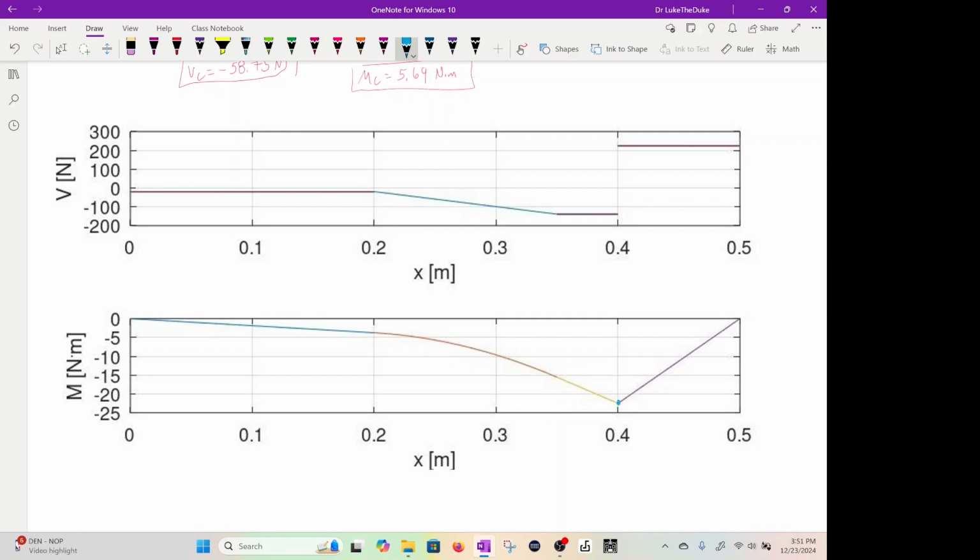So you can use that moment in the equations that we talked about before with bending, with sigma max is M over the section modulus, S, and you can figure out what your maximum stress is. Then you can go back in the tables and say, we can use steel because it's greater than that stress. Okay, so you can almost design that shaft.